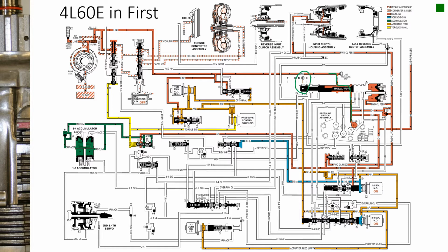In these following slides, we're going to review what's going on with the pressure switch assembly, but we're also going to look at the forward clutch accumulator. And this orifice 22 plays an important role, and this valve called the forward abuse valve, because all these things are in line with the clutch that we're going to apply, which is the forward clutch assembly in the input drum. That's what really happens when we shift into drive, and that gives us first gear. The only thing we have to apply is that forward clutch.